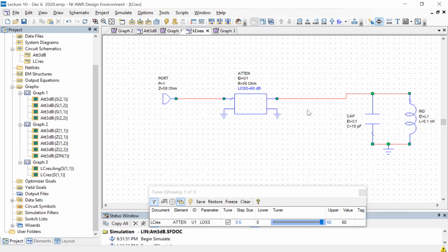So what you do instead is put a device next to this thing, a circulator or a directional coupler, which allows you to separate the ingoing wave and the outgoing wave at the low temperature. Then the outgoing wave is sent through a different path, which has amplifiers instead of attenuators. I will be discussing this in the next class in more detail, and we will again see what the good practices are, how to do it, and what the problems are when you do that.